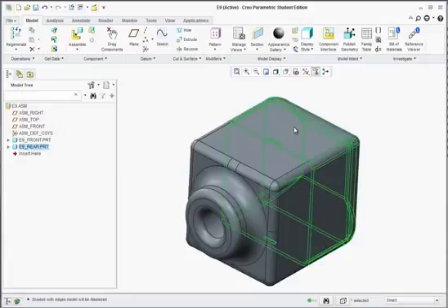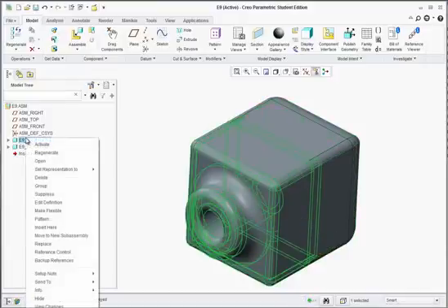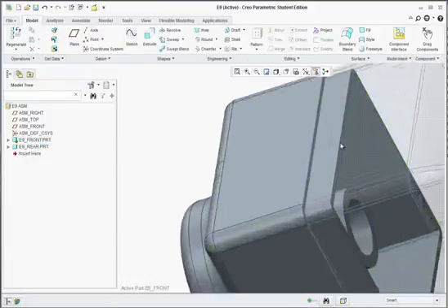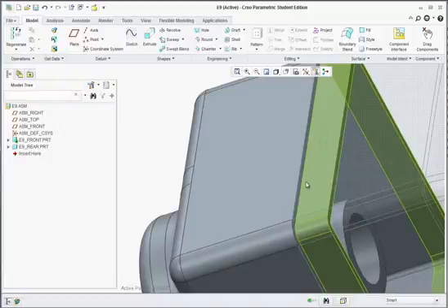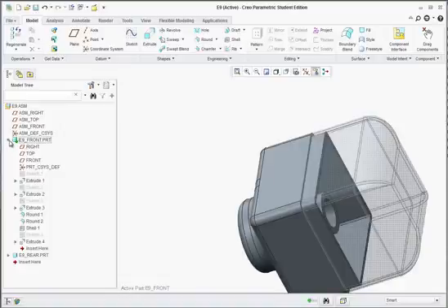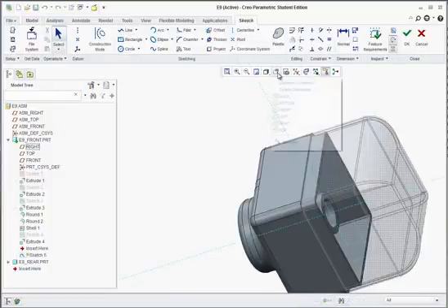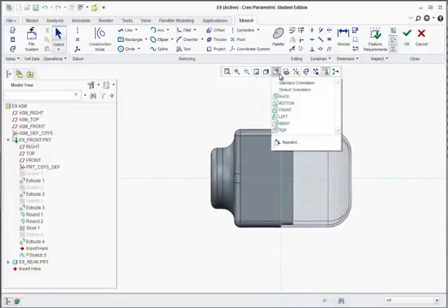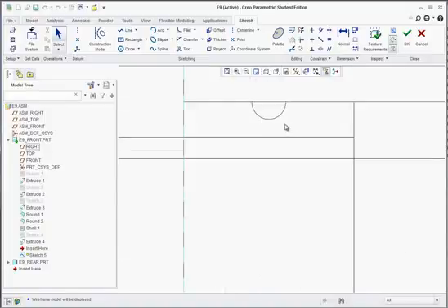Now we're going to click on the E9 rear, E9 front, and activate the E9 front because we need to put those same little pockets, or female side, in this area. So we could do the same thing. From the E9 front, hit the little arrow and select the right plane, start a sketch, and let's go normal to. So we'll go to the right orientation. We could go to wireframe, and we could see those little notches there.